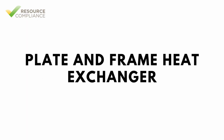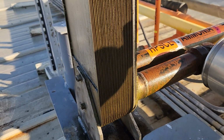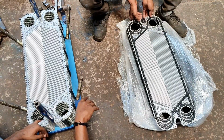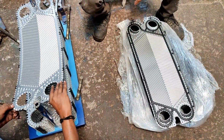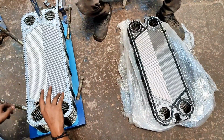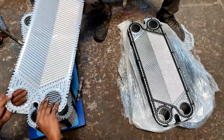A plate and frame heat exchanger is a second type of fluid cooling evaporator that is commonly used in refrigeration systems. These fluid coolers are popular because of their compact size, high efficiency, and ease of maintenance. Plate and frame heat exchangers consist of a series of thin corrugated metal plates, typically made of stainless steel. Each plate has a gasket that seals the plate edges to ensure the fluids do not mix. Small plate and frame heat exchangers are often seal welded to negate the need of gaskets altogether.